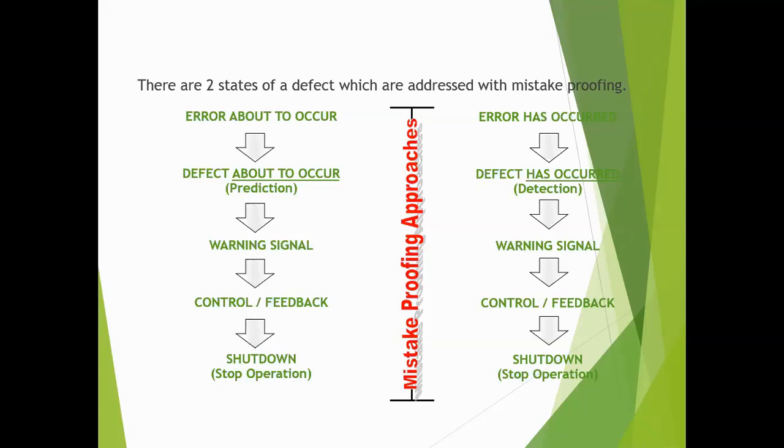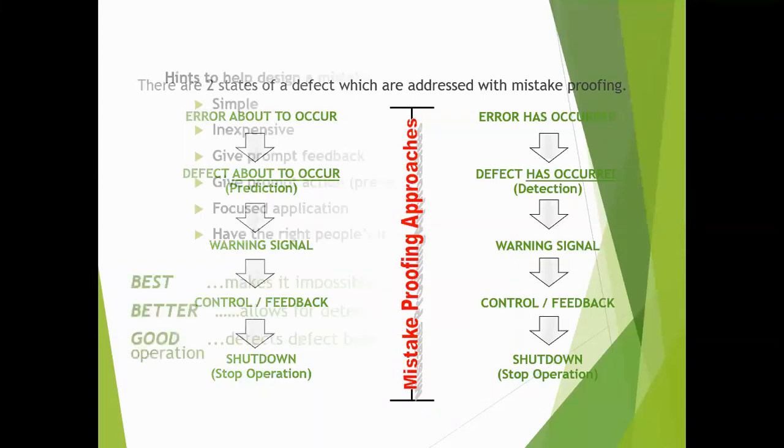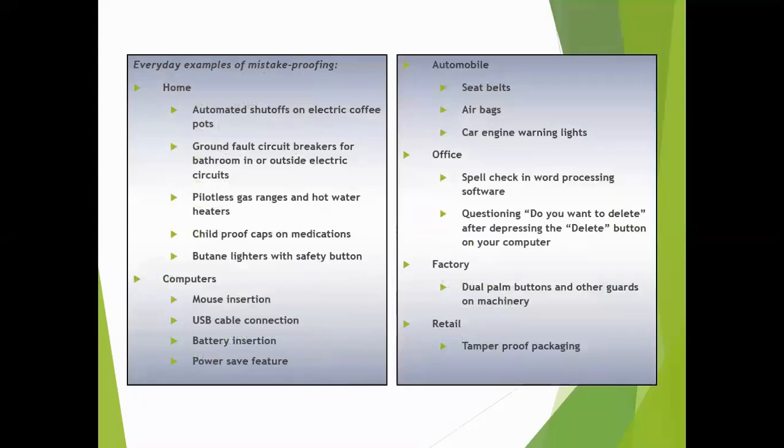And that's called a warning signal. And then you immediately go and inspect what is happening. We stop the production immediately, fix the problem, then only we start the production again. We do not wait for defective parts to come out, right? That's called mistake proofing. We stop the operation as soon as we get a warning so that no more defective products get produced. That's one example of mistake proofing.